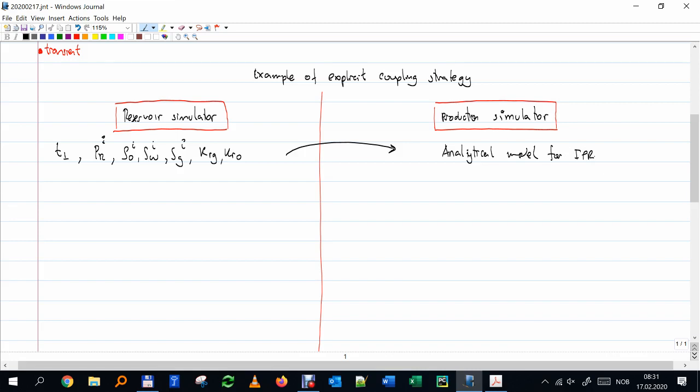I have made some analysis and found, for example, that I can use this back pressure model that we have used before: Q = C (PR² - PWF²)^n. In this case, if I was using that equation, I simply need to update reservoir pressure, right? Because the C and the n really don't change.